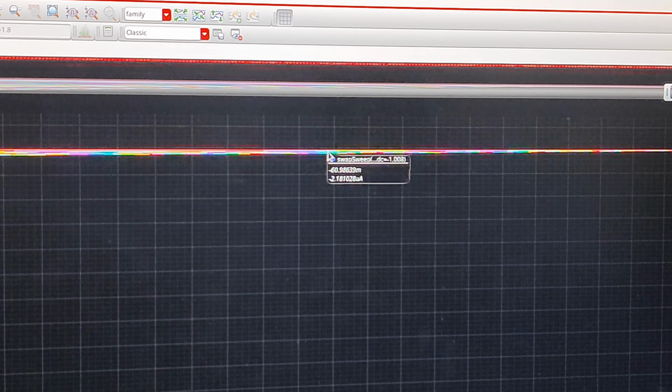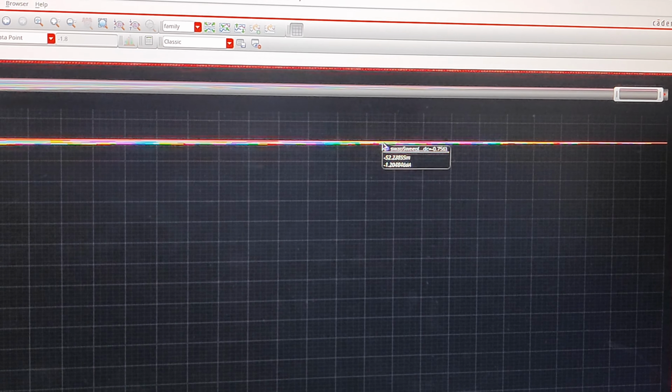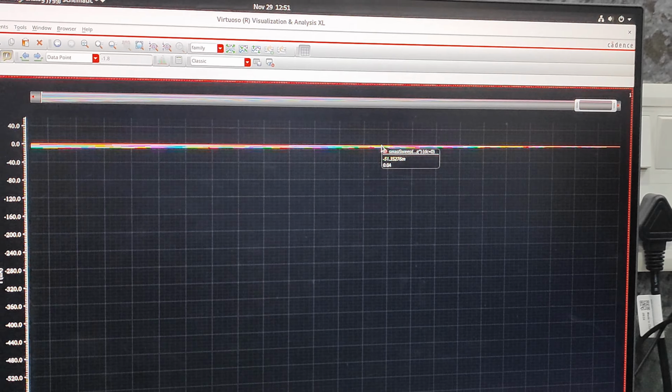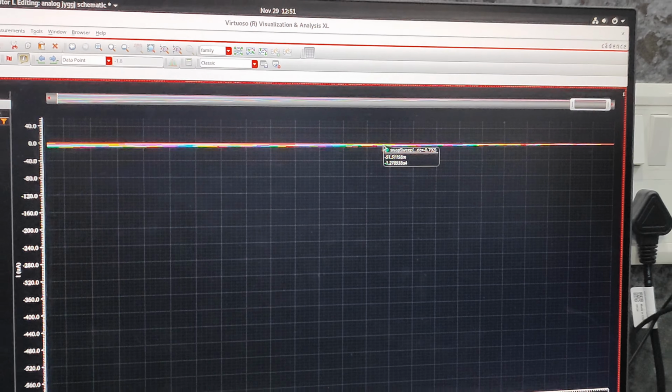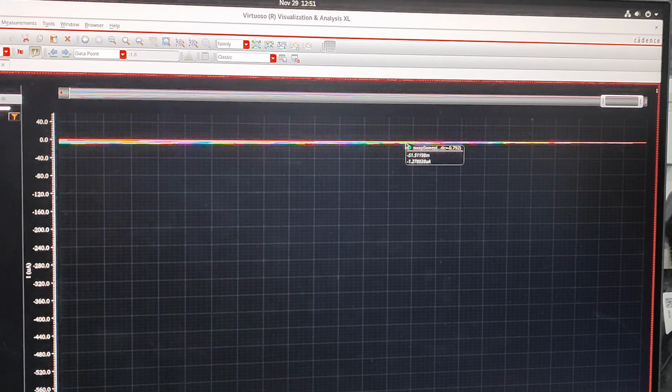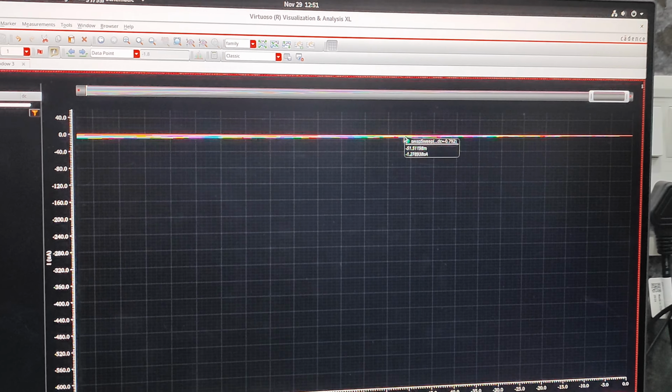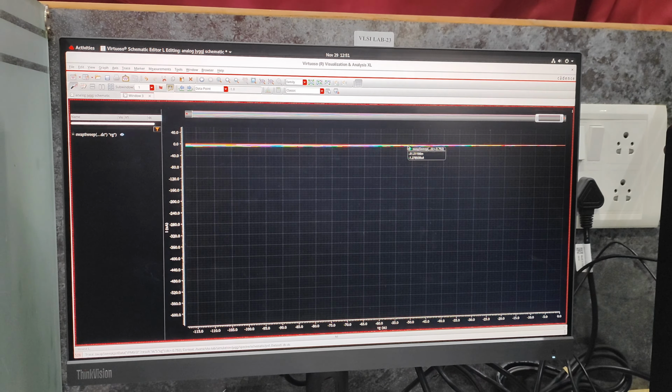It's still 0.0 amp, so that can't be. You see where current is starting, it will be somewhere over here. It's still 0 amp. So you just move over here, see here, where it started now, that particular point. To be more specific, around minus 51 or 50 millivolt approximately, you'll be getting the threshold voltage. Okay, so this is the experiment for PMOS analysis.